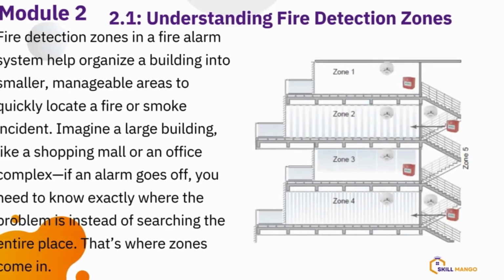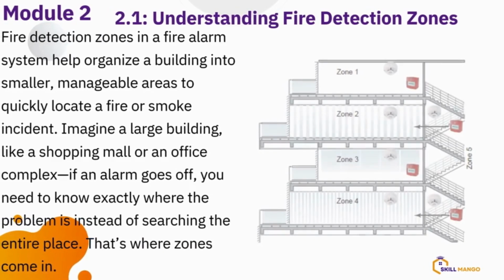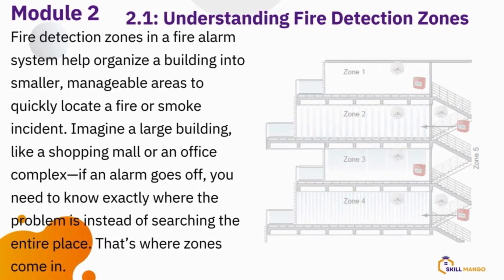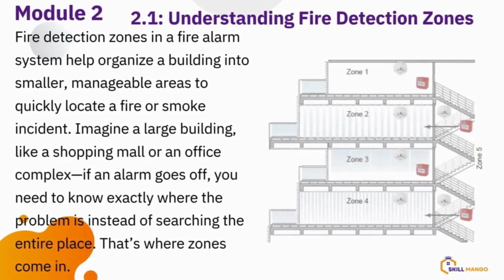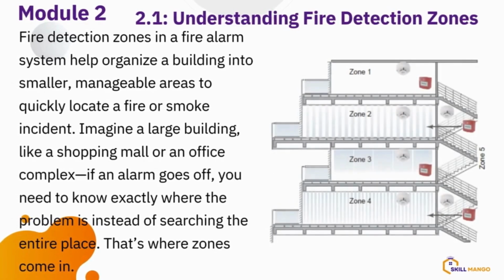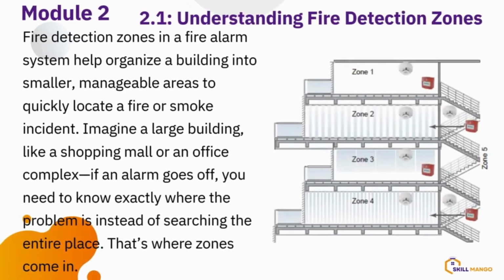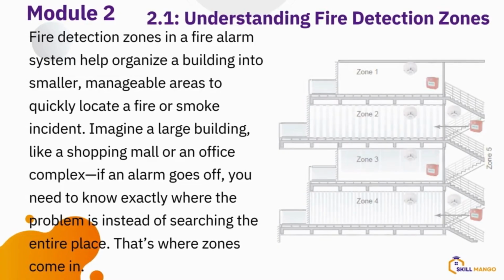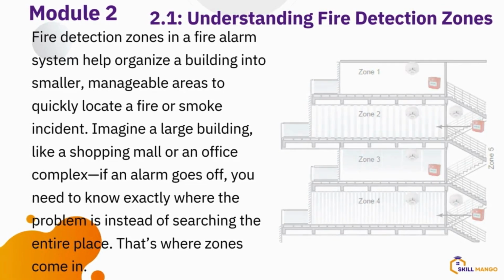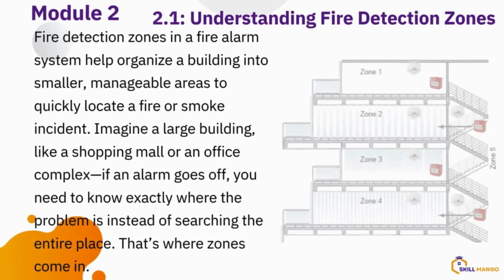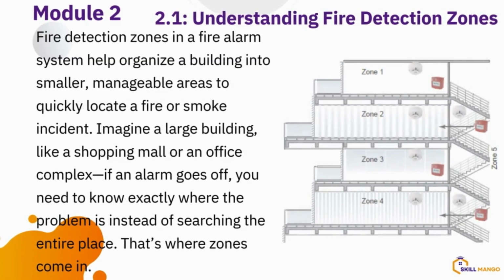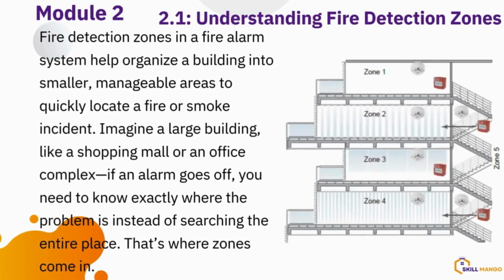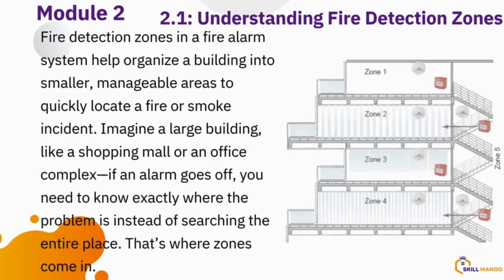So all the equipment on zone 1, we are putting them on the last floor, which is zone 1. Meaning that based on this diagram, we only have one device, which is one smoke detector and one break glass. So the two devices on zone one. Okay, let's pay attention to zone one. Now, this cable from the zone one smoke detector and zone one break glass are coming down to the panel. All right.